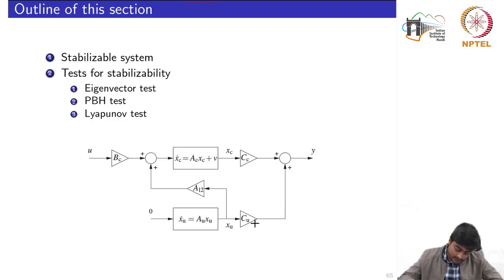So this figure demonstrates the block diagram decomposition with which we have concluded. We see that U only has an impact on the controllable states, and through any path U does not have any impact on the uncontrollable states. So you cannot influence the XU states.